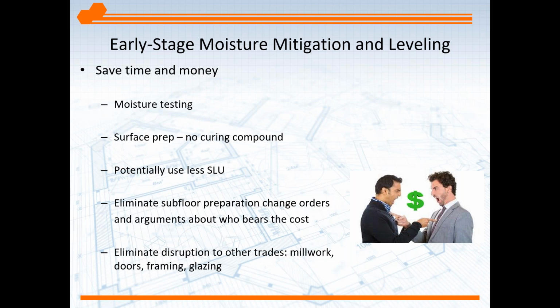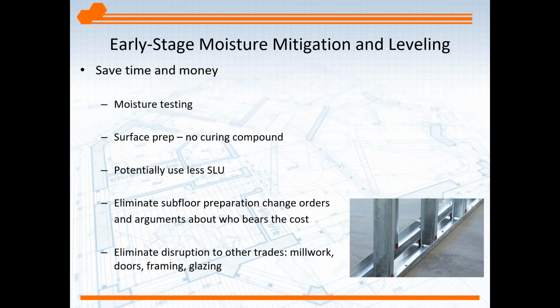And in addition, flooring has certain flatness requirements. In the case of porcelain tile, you want a slab that has variation less than 1/8 inch in 10 feet. But there's a lot of trades and their products that are affected by floor flatness. So rather than, again, at the 11th hour of floor installation or other materials, you've got that corrected, so scheduling is not interrupted to take remedial steps relative to moisture and curl of that concrete slab.